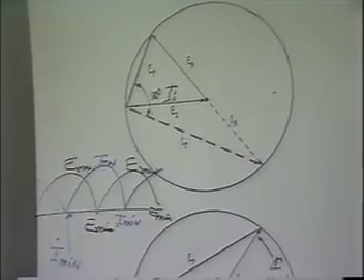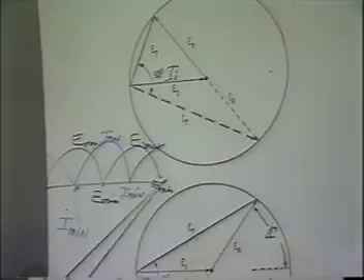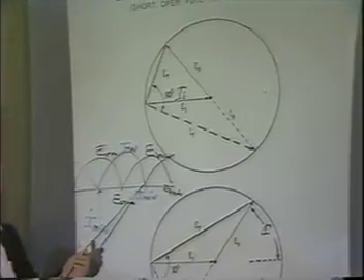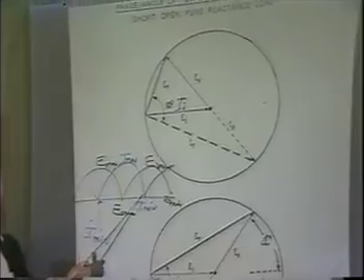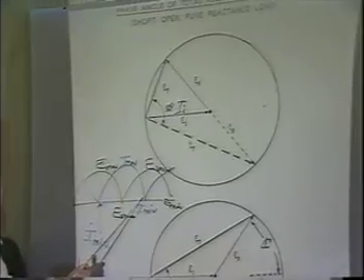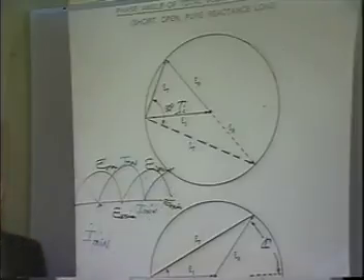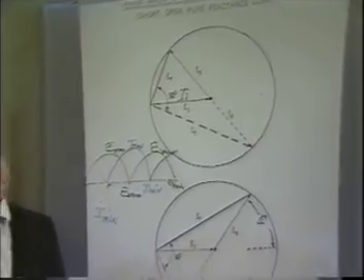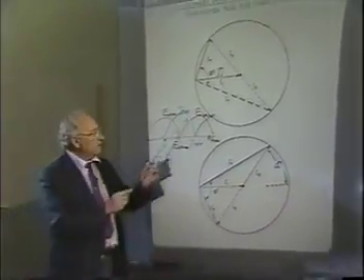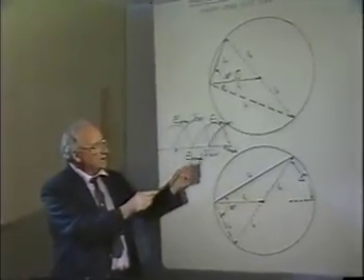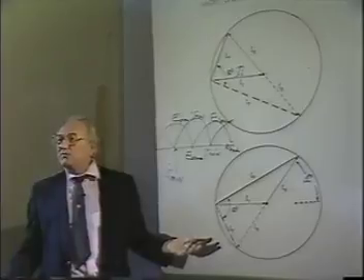Notice another interesting thing. No matter what you connect to this transmission line, what's the maximum amount this minimum can shift? The maximum number of degrees this can shift. Well, if I have a short here and I put another short on, does it shift? No. If I put an open on, how much does it shift? 90 degrees, right, because I'd put the open here. You can see that that's 90 degrees from this. The maximum it would ever shift is 90 degrees.